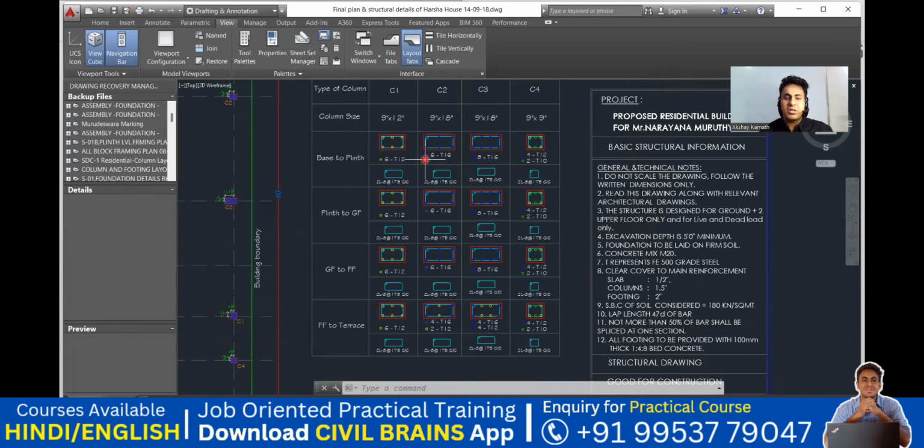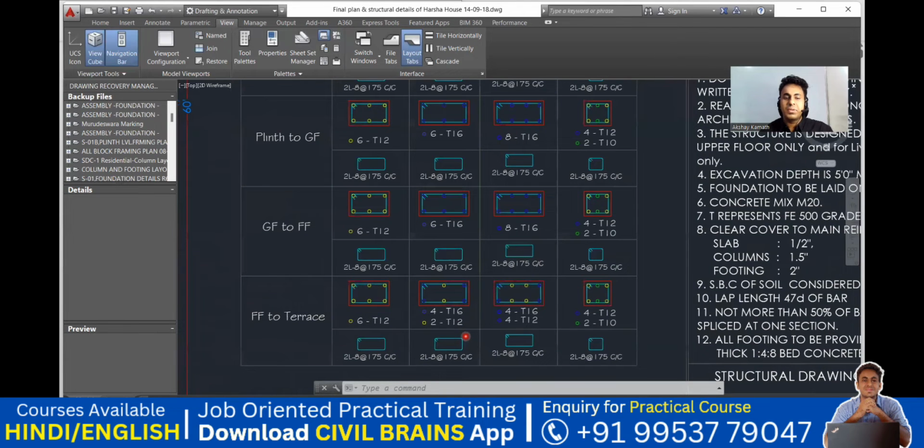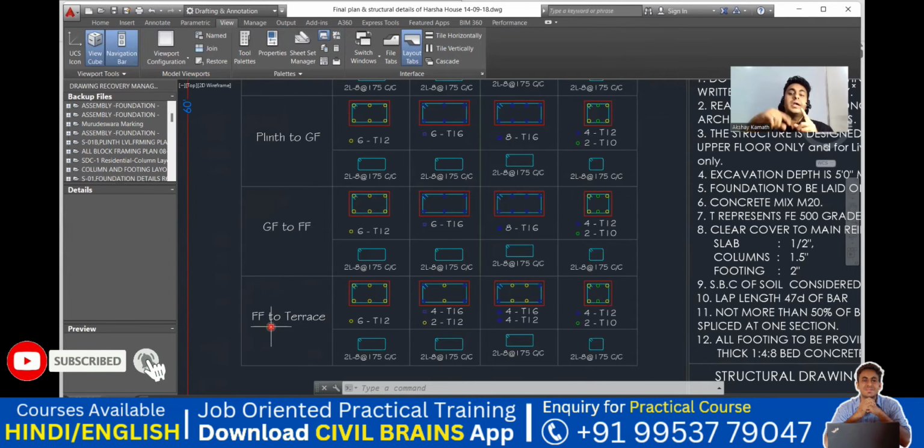See here also 16 of 6, 16 of 6, 16 of 6, and then see small changes they have done here. Instead of 16 of 6 in the ground floor to first floor, you are providing a 16 diameter 6 bar. When I come into the first floor to the terrace, what they have done, they have not done 16 of 6. Instead of that, they have given a 16 diameter 4 bar, and the rest 2 bar they have made it of 12 diameter. Why is that so? Because when you're coming to the terrace portion, your load is very less. When the load is very less coming on the column, the steel requirement is also less. So instead of using the same diameter, instead of 16 of 6, we have reduced that from 16 of 4 to 12 of 2.